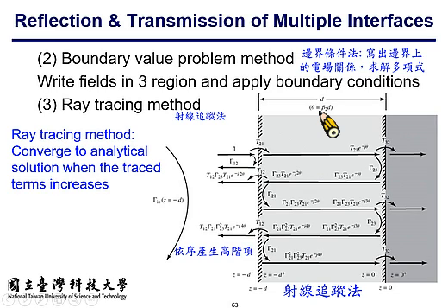So as you can see, it becomes the direct reflection. The direct reflection part is the incidence times the reflection coefficient at the interface, gamma 1,2. The second term can be traced as incidence, transmission, reflection, transmission. So the second term is tau 1,2 times gamma 2,3 times tau 2,1 times the exponential of minus j2 theta.